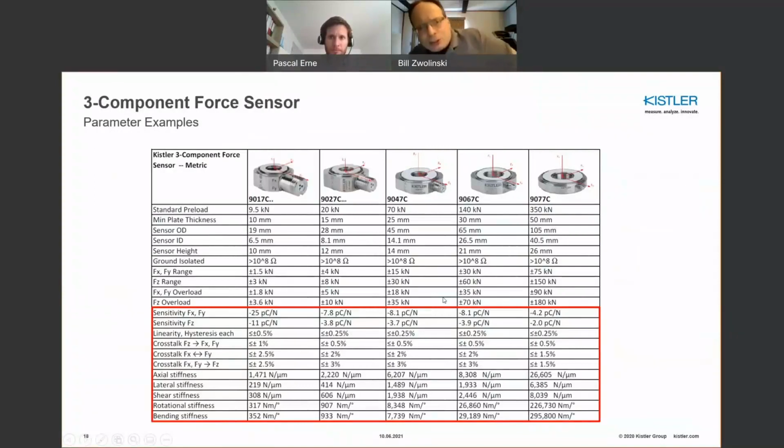So I just show this picture of force sensors. These are three component force sensors, and really just to look at the terminology. I talk about things to do with sensitivity, which is usually pretty straightforward, but linearity and hysteresis are some of the key errors in any sensor. Linearity is a function of input versus output, and is usually done at a single frequency, for example.